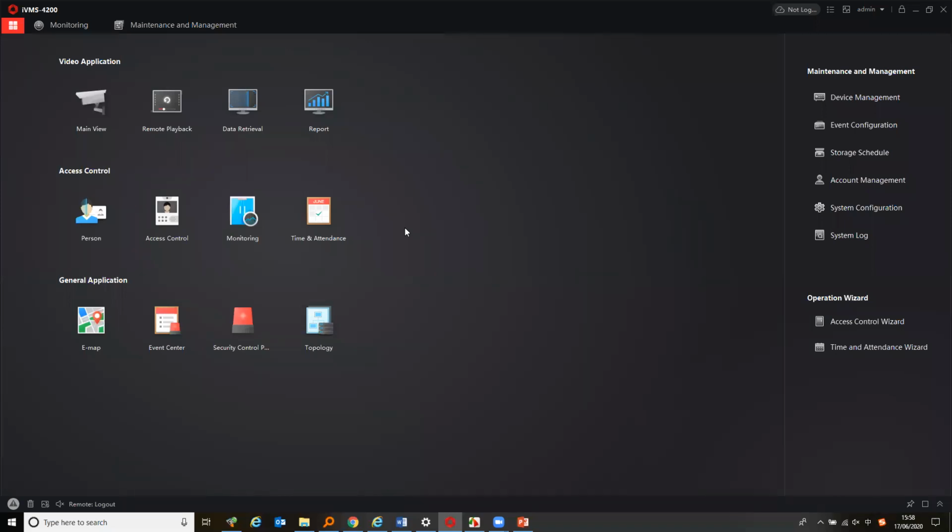Authorized mode means it is an access control terminal. So for all the access control terminals, you need to first create the person. So there's an access control setting here. You need to first create the person database, the person library, and then download all the persons into the access control terminals. And then after you've done this step, you can go into the monitoring for real-time monitoring. And if you want time attendance, you go into the time attendance setting. So this is quite logical here.